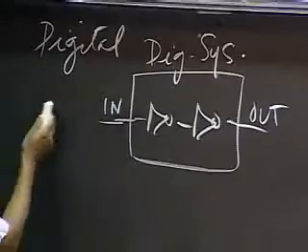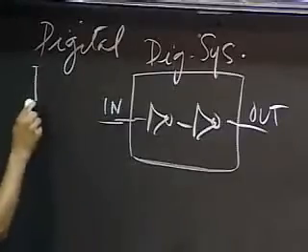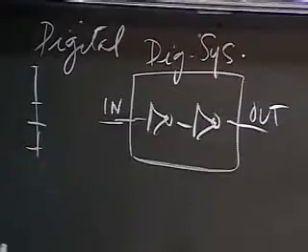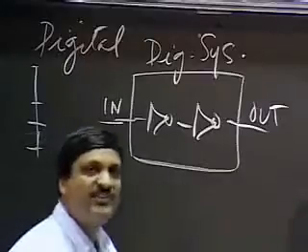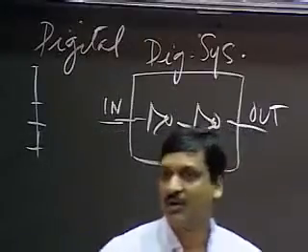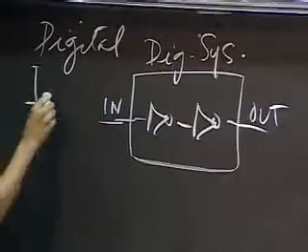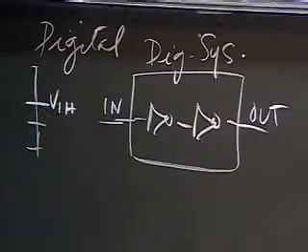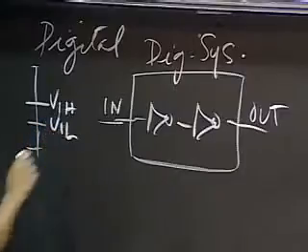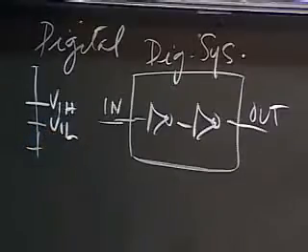And the discipline we described comprised of signals adhering to certain voltage thresholds, so that all the components in the system could agree on what comprised a 0 and what comprised a 1. Okay? So the way we did that was we said that we would have a threshold called VIH, V input high, another threshold called VIL, V input low.